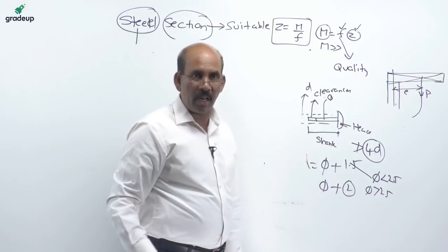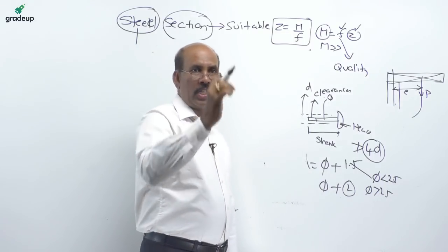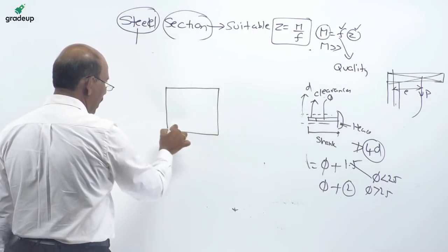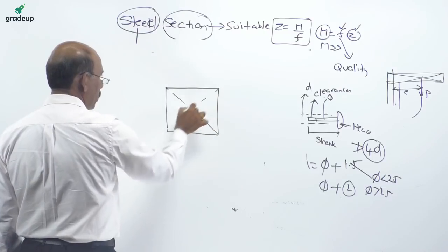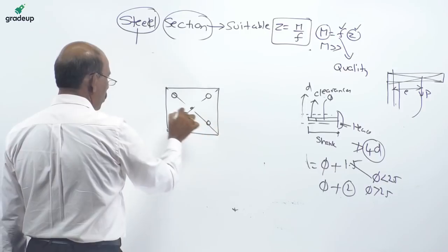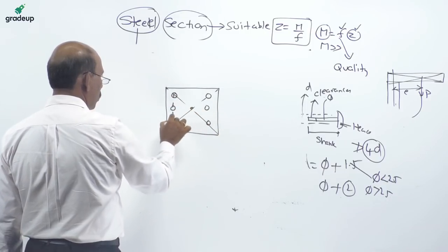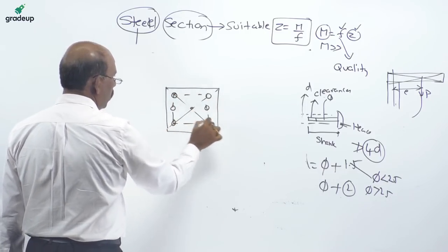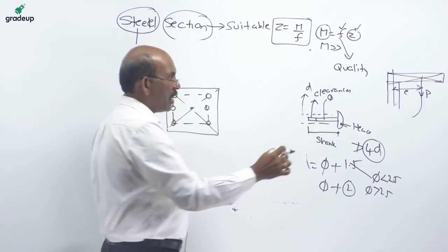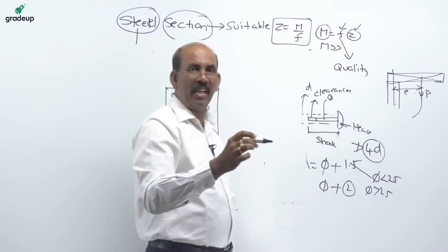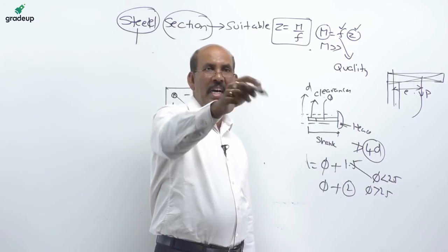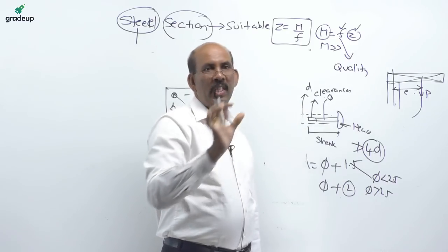With reference to Mr. Aryan Raj, good question. This is your connection if I say here. So, this is the center. Your bolts are here. So, these bolts are here. This particular eccentricity, as I mentioned here, this is an eccentric connection. Definitely in an eccentric connection, the effect in the lap joint is neglected and the grip length is nothing to do with this particular one.